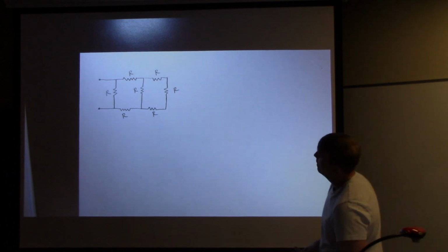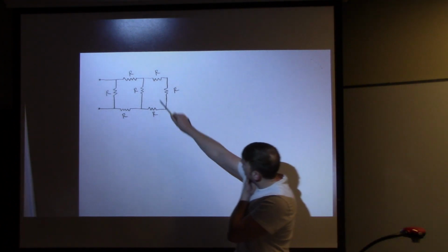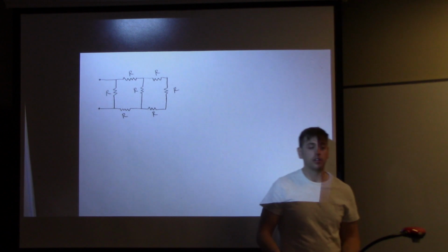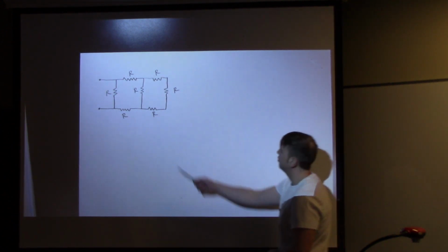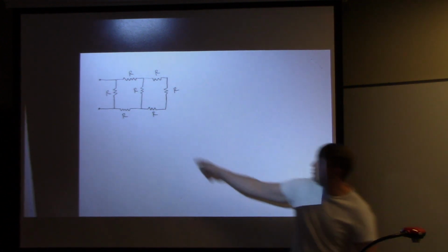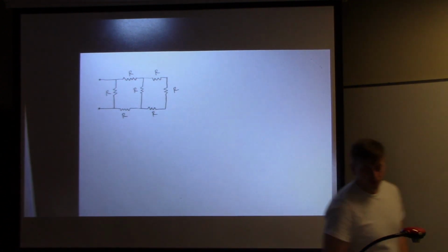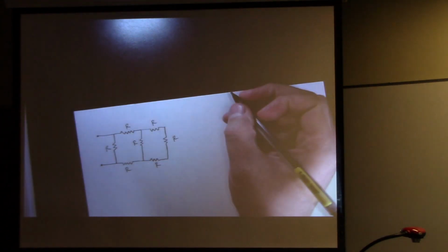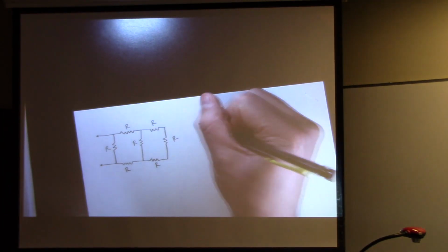So the question for us is, what are the first set of resistors that I can combine? Where you should be looking is right here at the rightmost part of the circuit, because clearly we have three resistors, which are in series, because they're connected along a single path.